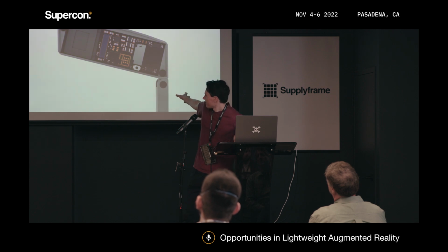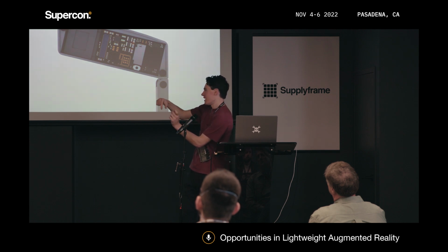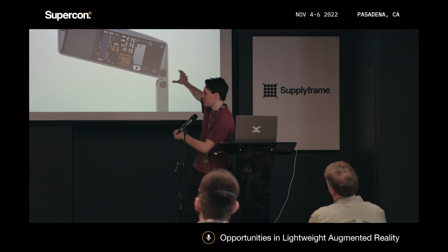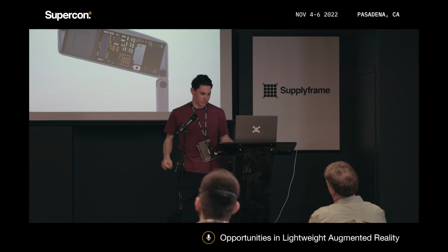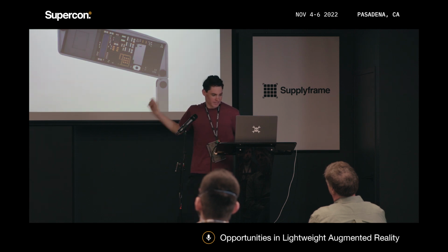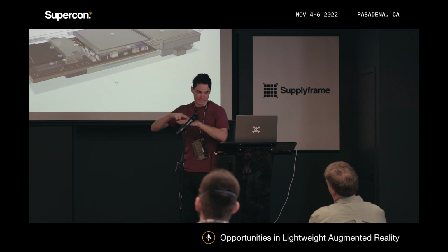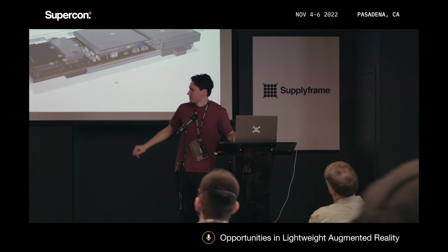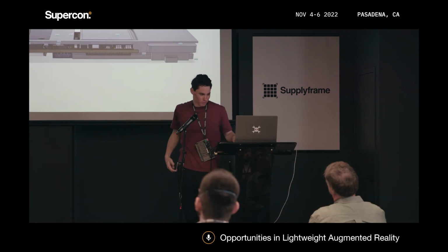So essentially, I'm envisioning here a sort of brim design which sits over the top edge of a glasses frame. So rather than having the board vertical on the side, I said, well, what if you put the board horizontal, sort of in front of the user's eyebrow? And if you continue making your board narrower and narrower over time, then you could make this look quite compact. So the display sits next to it like that. It ends up stacking into this relatively neat and tidy little arrangement with the display flex cable folded like that.